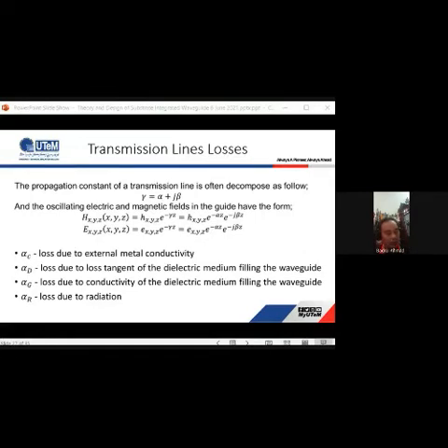In that way, all the wall thickness is much thicker than the skin depth of the signal, so no radiation will appear. So this is in fact one of the advantages of closed waveguide compared to the open line such as microstrip. Out of these 4 losses, only 2 contribute to losses for waveguide. As you can see, the SIW replicates what the waveguide is. So out of 4 that contribute to losses in microstrip, for SIW we have only 2 losses that contribute.